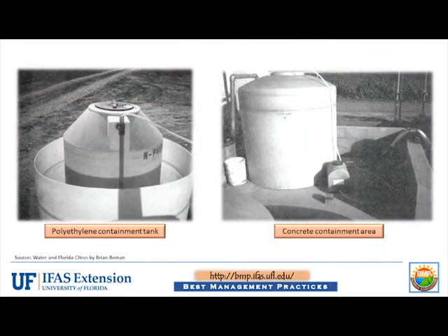Chemical storage tanks must be located in an area that is remote from the well site or surface water supply. Tanks should also be sloped so that contamination of the water supply will not occur in the case of tank rupture or spillage. The chemical supply tank should be constructed of materials that will withstand the corrosive chemicals stored in it. Some chemicals and tank materials are subject to degradation by sunlight. Therefore, chemical tanks are often painted to exclude sunlight.